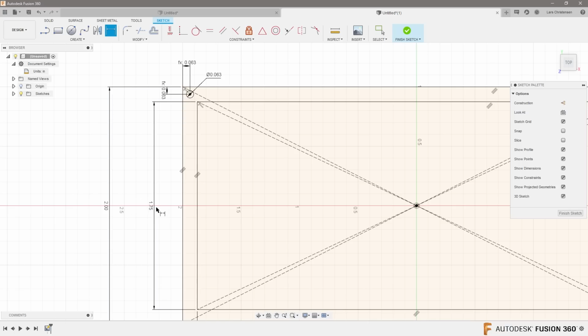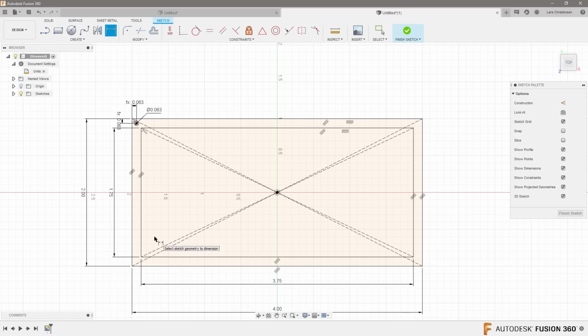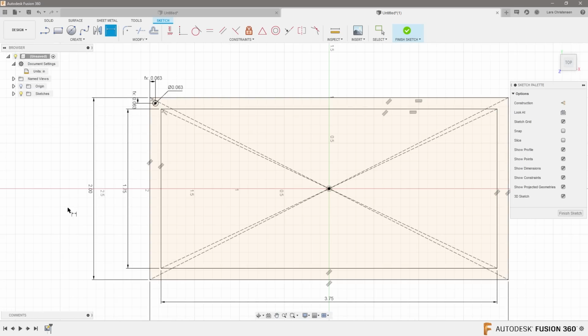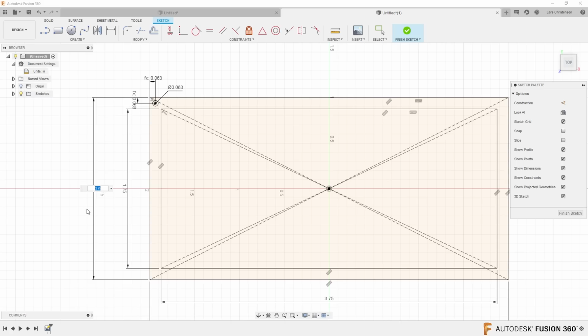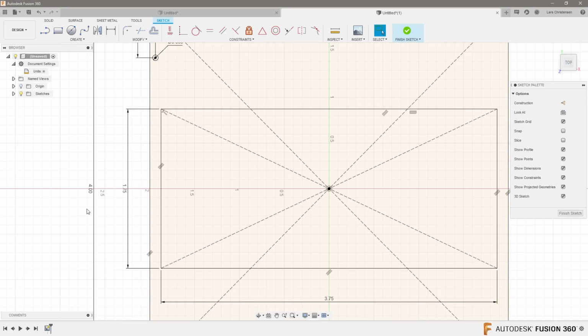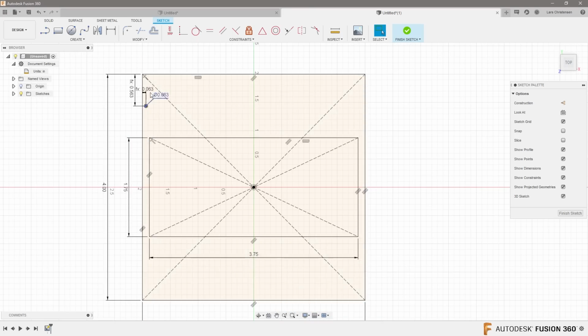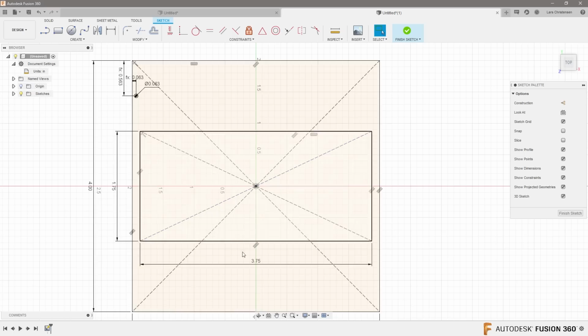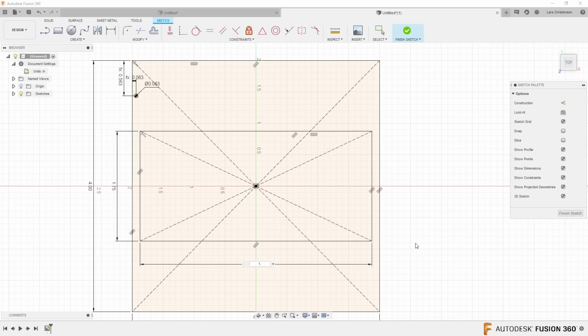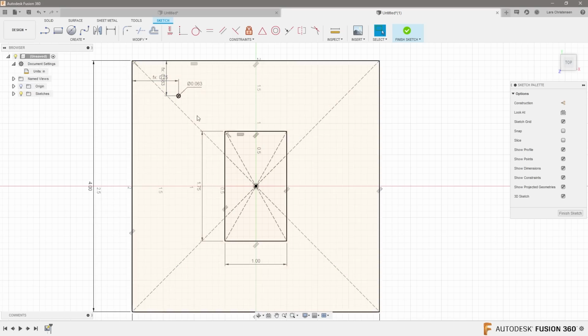Now, anytime we're changing these dimensions, that will reflect on these holes. Now, I'm assuming, Eric, that you actually maybe need 4 holes around here. Actually, so what I would do now is I would actually test it. That's probably the right thing to do. So if we go in here, we double click on 2, and we made that 4 also, you will see that this distance is capped between these two with that hole. But it's going to keep the x direction in there. Of course, if I change this to 1, then you will see that it's going to do that math.